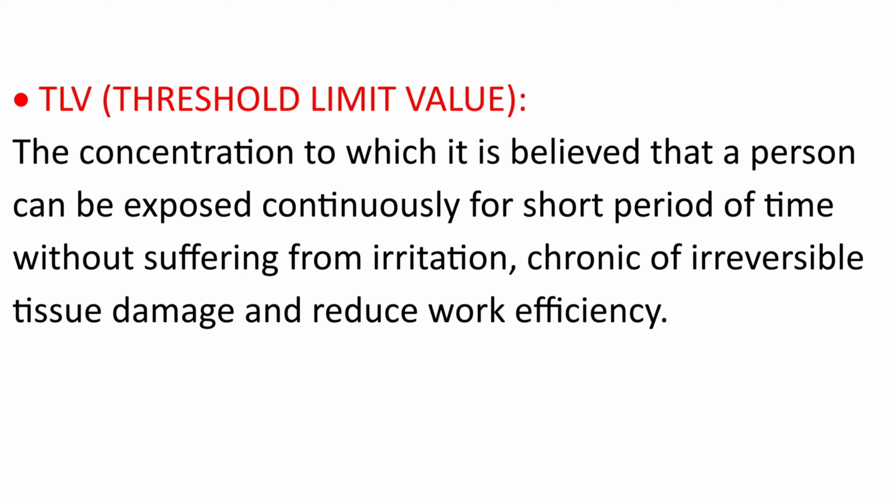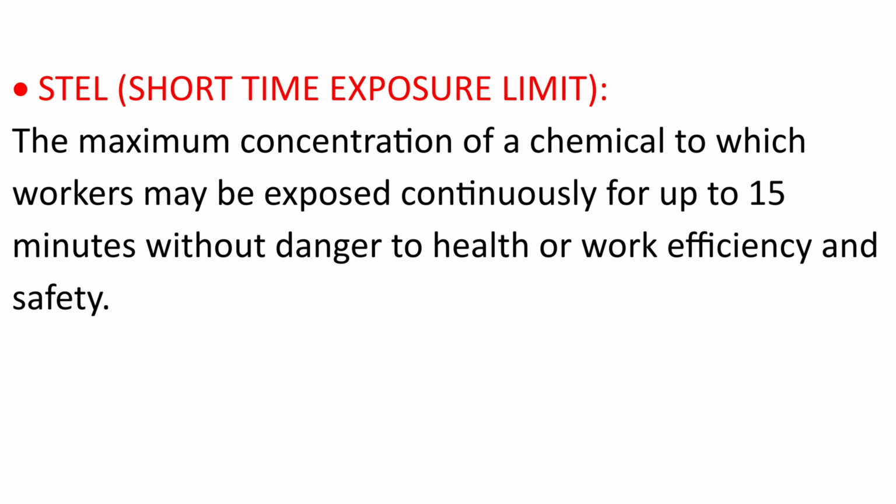Question. TLV, threshold limit value. Answer. The concentration to which it is believed that a person can be exposed continuously for short period of time without suffering from irritation, chronic or irreversible tissue damage and reduced work efficiency. Question. STEL, short time exposure limit. Answer.